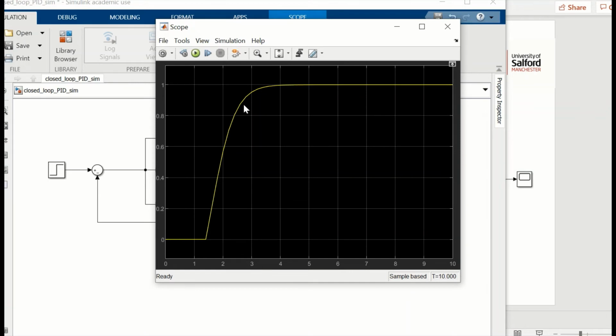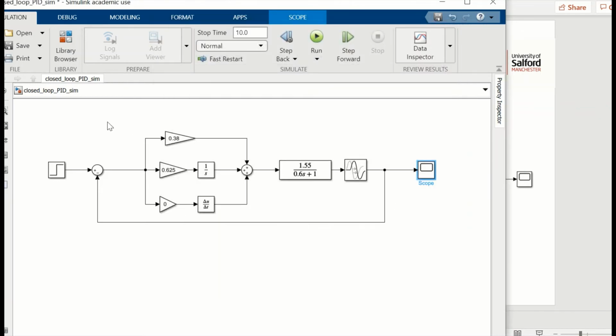That's not too bad, almost like critically damped. You could say gain margin of 4 isn't exactly that, but it's not far off. So gain margin of 4 won't tend to give you any overshoot, just nice and damped, but not too slow either. So again, you could copy that one.